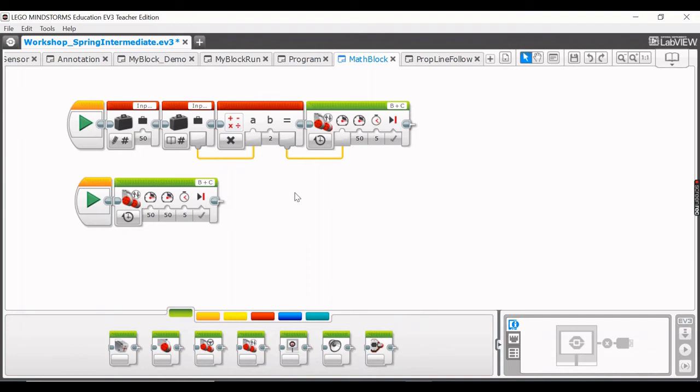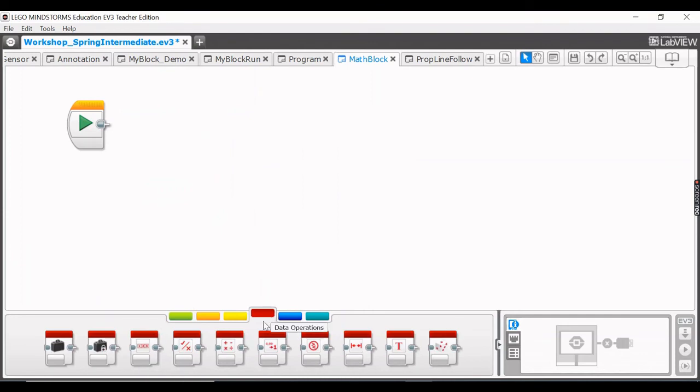Okay, now, after watching those two videos, you saw how it turned to the other direction this time. And that's all because of this proportional factor. This input and this output have one thing in common, that they have to do something with this B value. And that's because we're multiplying it. And that's basically the gist of scaling and using the proportion in EV3 Mindstorms. Now let me show you threshold values.